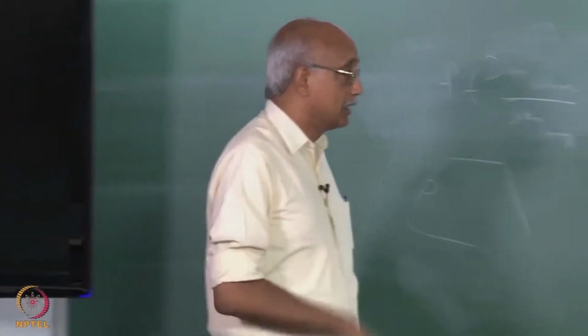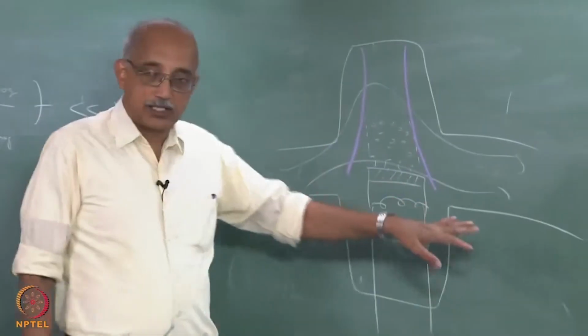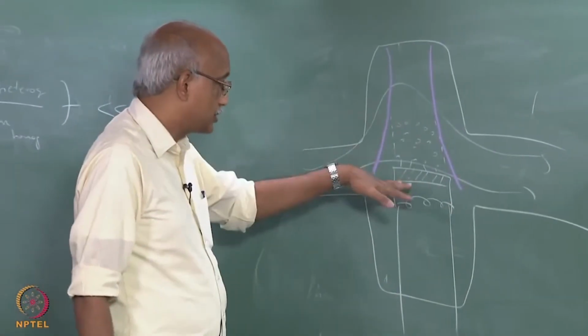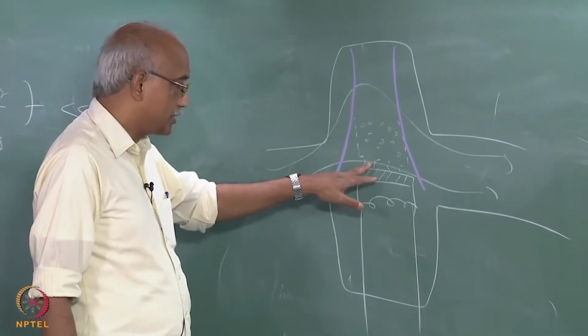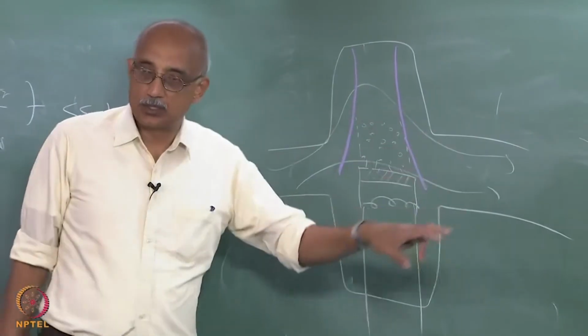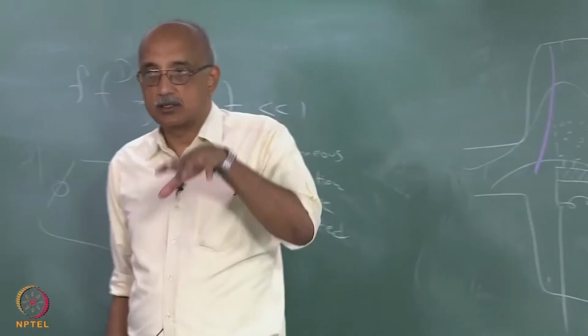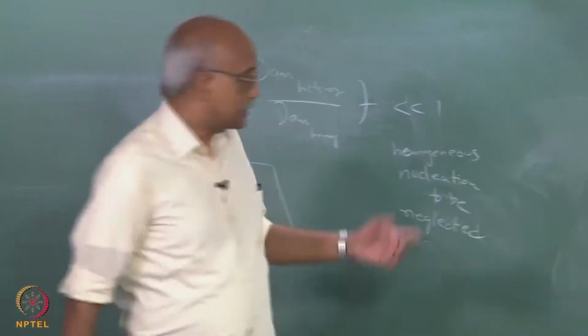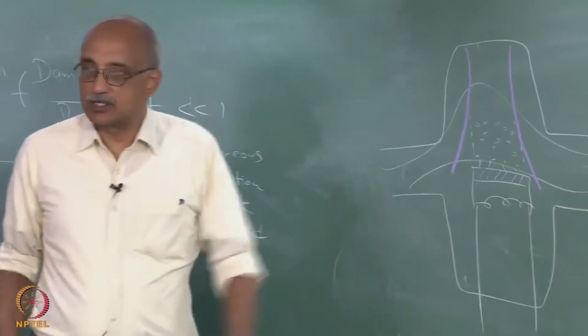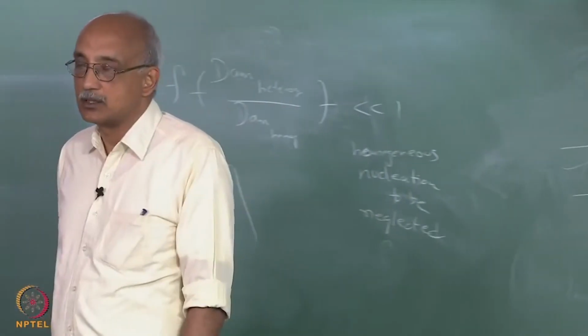So, here again the stagnation flow configuration helps, because when the flow is this way, even if an aerosol hits the substrate and rebounds, it can again be directed back to the substrate. Whereas, in this type of flow situation, once it rebounds, it is gone, you have lost the material.